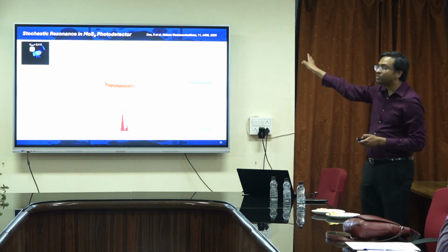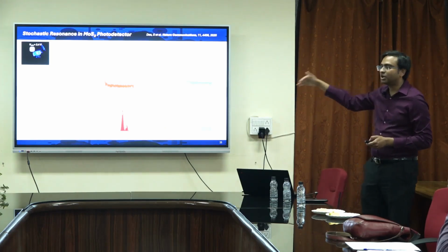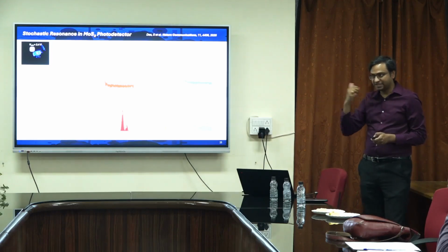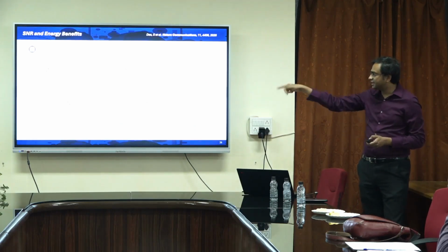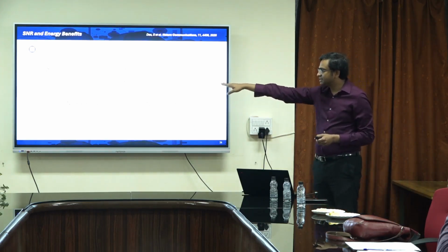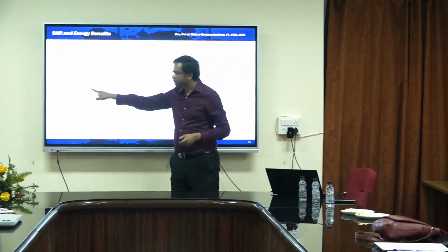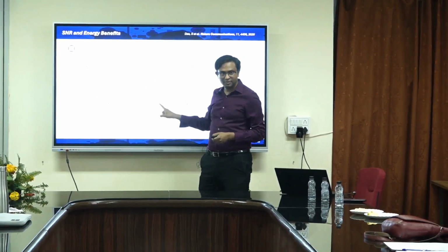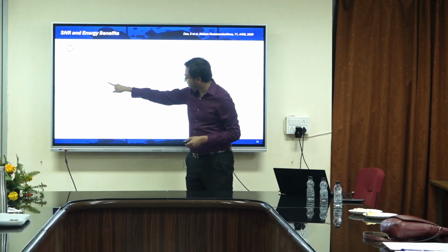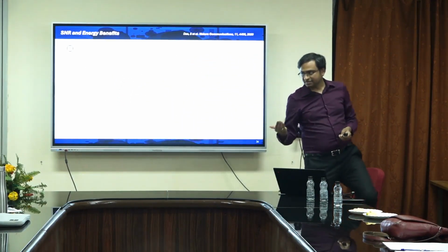And if you have too much noise, then again everything is lost because the floor is now much higher. That's what we just experienced, and this is a quintessential curve for stochastic resonance. No noise, the signal cannot be detected. You see over here the signal-to-noise ratio is low. Too high noise, it cannot be detected. Only with a certain amount of noise can I detect it, and that is stochastic resonance.